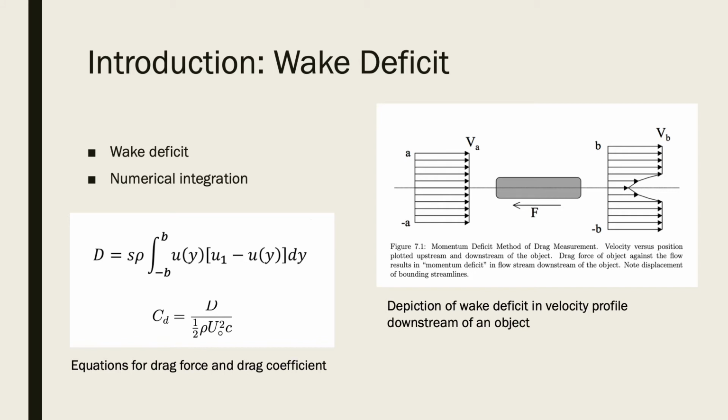Another way to measure the drag on an object such as an airfoil is to measure the velocity profile of its wake. Assuming that the static pressure is constant along the control volume and that the momentum is conserved, we expect that the effect of drag is evident in the momentum deficit in the wake of an object. Applying numerical integration to the momentum equation from fluid dynamics combined with a mass conservation equation gives us the following results for the drag force.